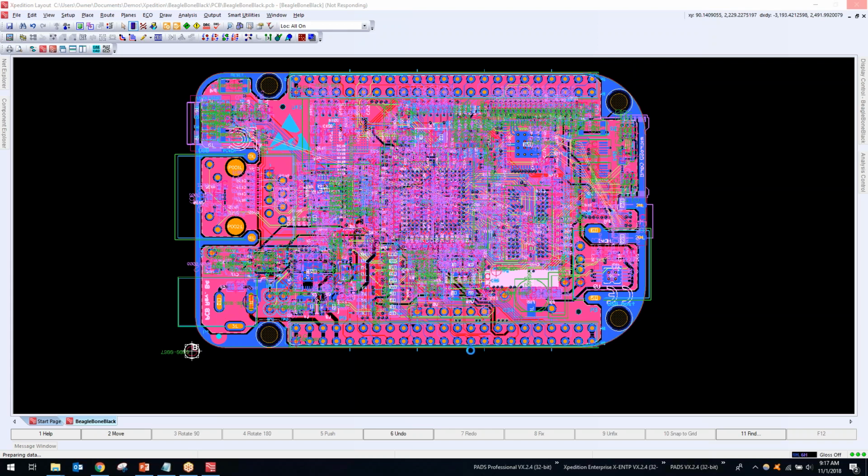All right, so what this is going to do is create an ODB++ file. So you'll see right there, we've got an ODB++ output being generated. It's creating this file for us and pushing it over into Valor, running those rules, and then giving us the errors back again, just in that Hazard Explorer. Very easy to work with.